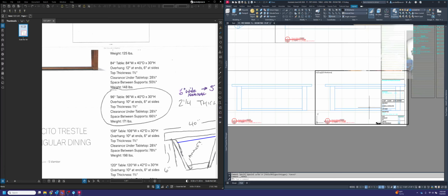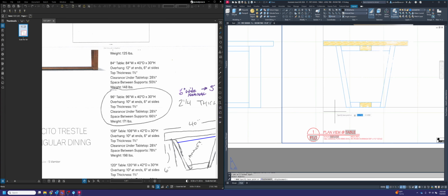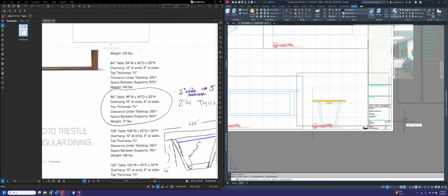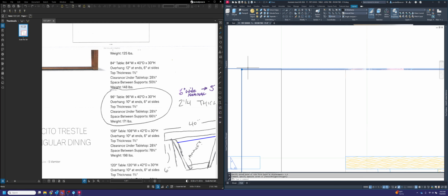Recap as well. Make sure that when you are copying your viewports, you use the AutoCAD version of the command COPY and not Control-C and Control-V, or you'll break the formulas that we have populated in there. So it's easy to do. I've done it so many times. I've seen other people do it too. But make sure that you're using COPY, not Control-C and Control-V for this.